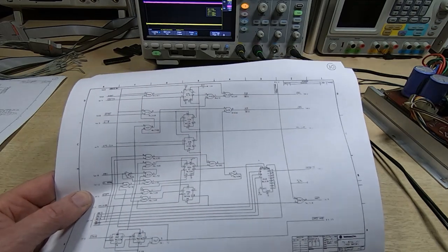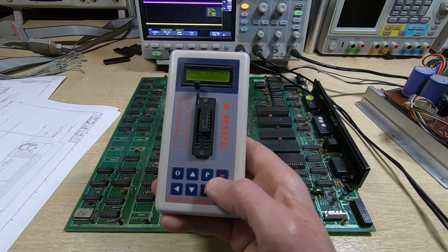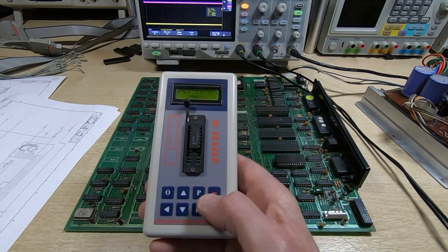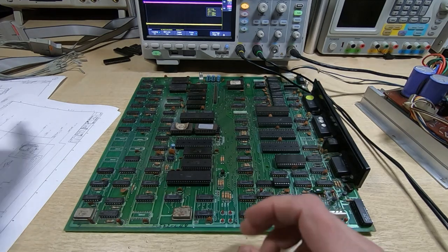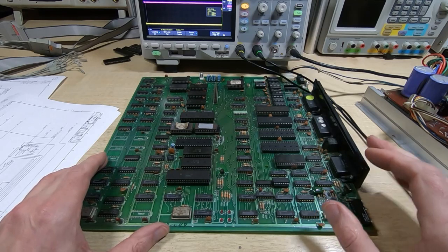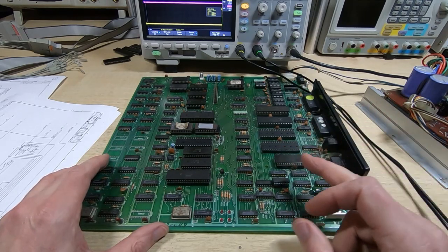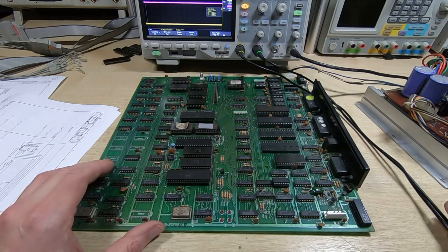So I took that IC out, put a new one in. This is the one I've taken out. If we do a test, it does indeed test as faulty. Another reason I try and get them out intact. So what we'll do now is we'll power the board up. It's not going to get all the way through the self-test, even if it gets any further, because I have certain ICs removed. But we'll see if it gets any further.